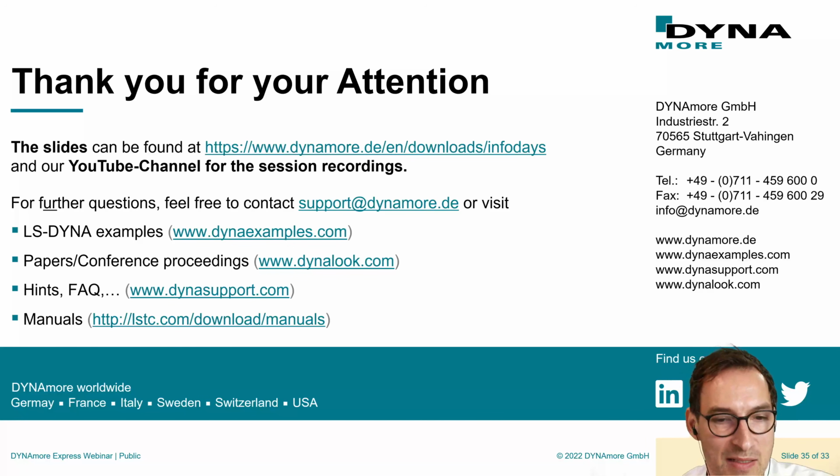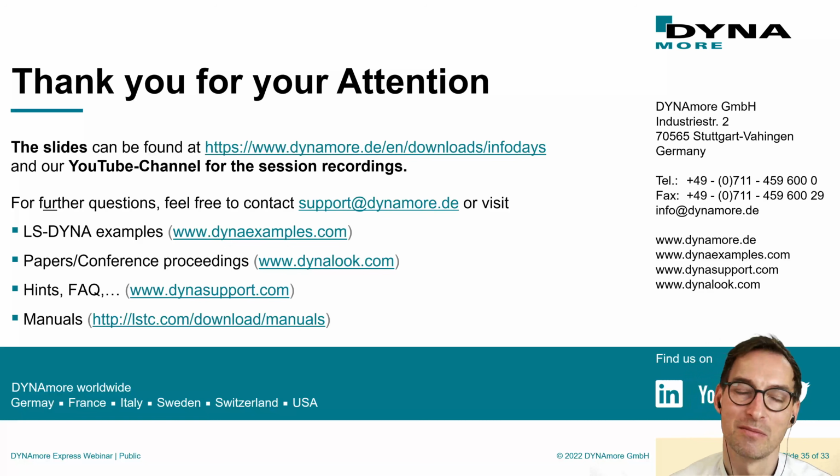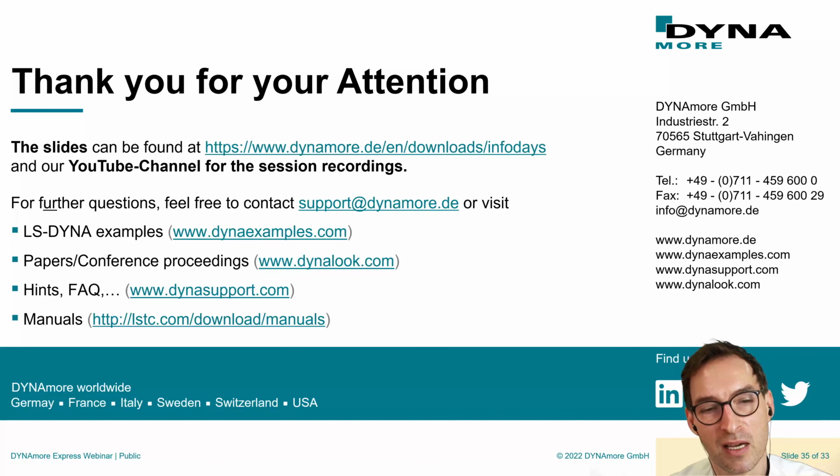There's a question regarding mass scaling, and that's a good question. I think mass scaling is possible, but to be honest, I'm not sure, and I was never using it. I'm one of these guys who's trying to avoid mass scaling. I'm mostly doing this multi-physics support stuff, so I'm not so much into these large simulations where you effectively do a lot with mass scaling. I think it's also possible to do mass scaling in ALE, but I'm not sure because I never used it.